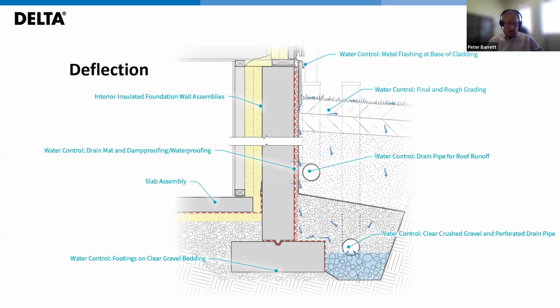This typically consists of a drain mat as well as perimeter drainage around the footing. I'd like to point out that perimeter drainage is very important when we're dealing with drain boards, because once we guide that water to a place, we'd also like to be able to carry it away. That is a critical part of a well-functioning water management system.